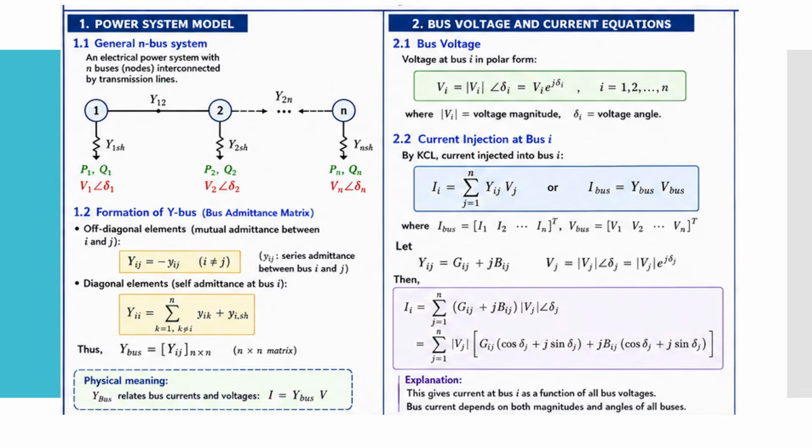So coming to the power flow problem using this admittance matrix, we can use the same principle that we have seen in that diagram to perform a power flow for n buses. For example, here we have a general n-bus system, so that we can form an n by n Y bus matrix, and we can calculate the voltage, power, current, and all things.